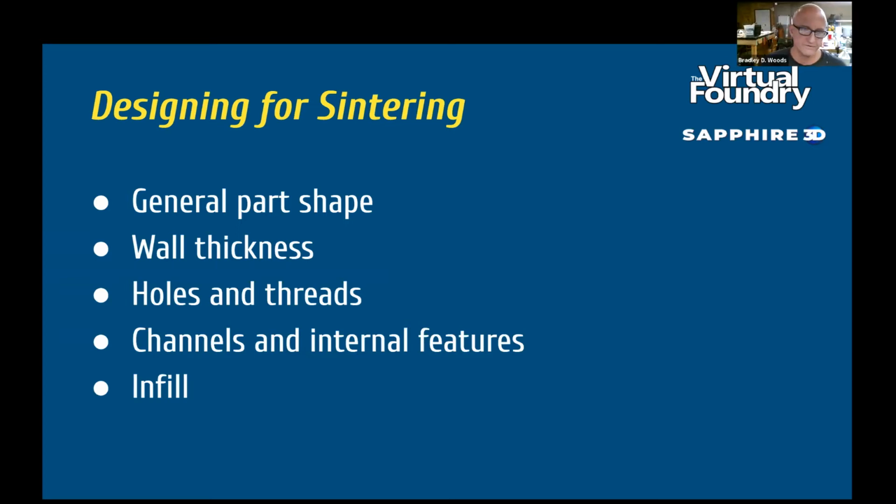Right. One of the key things that's unique about this process, like we said, is it's meant to be sintered at the very end of it. So all of the plastic that you put into the part while you're printing later needs to be taken out, and it leaves the part as a gas. So what can happen is if parts or walls are very thick, it becomes more and more difficult for the gases to escape from the center of the part, and it'll cause some distortion.